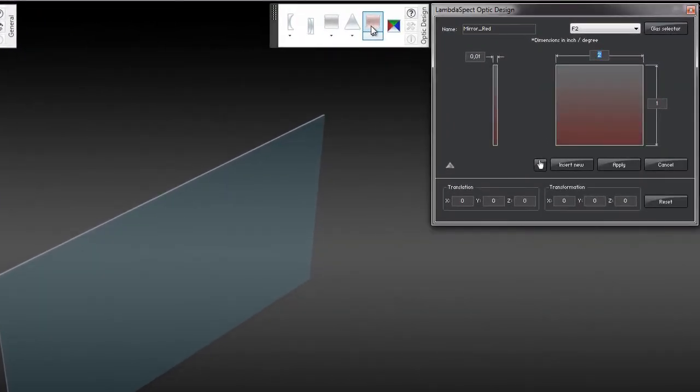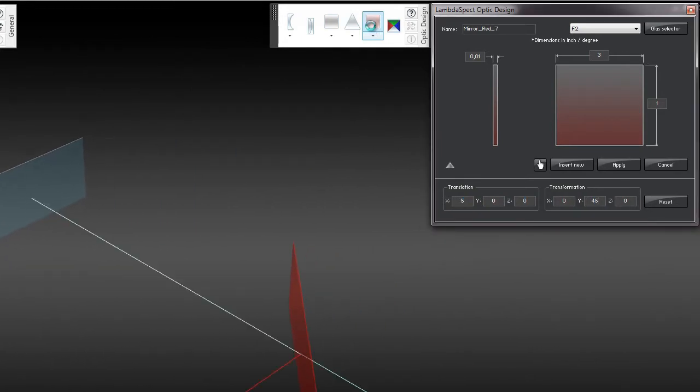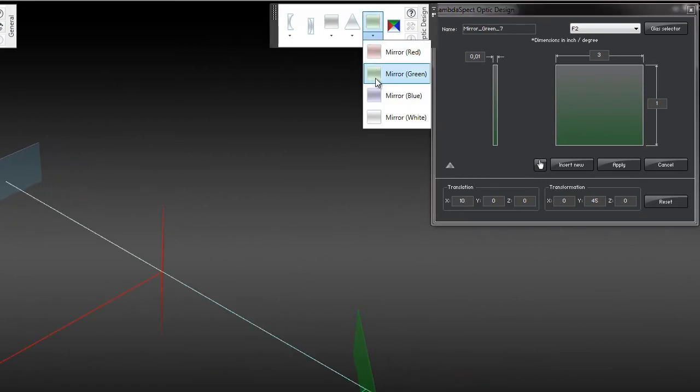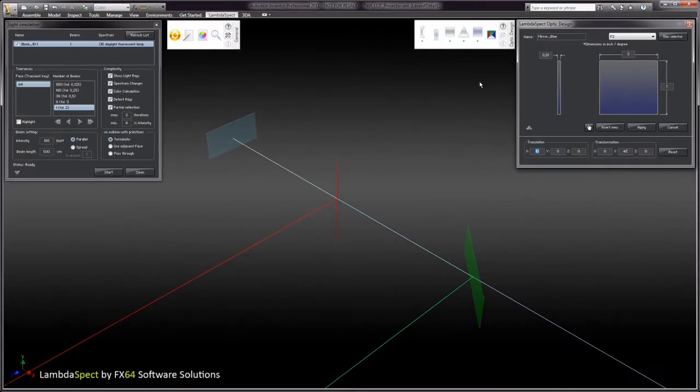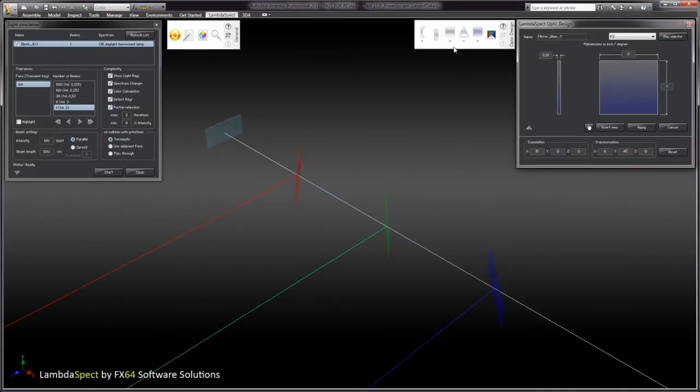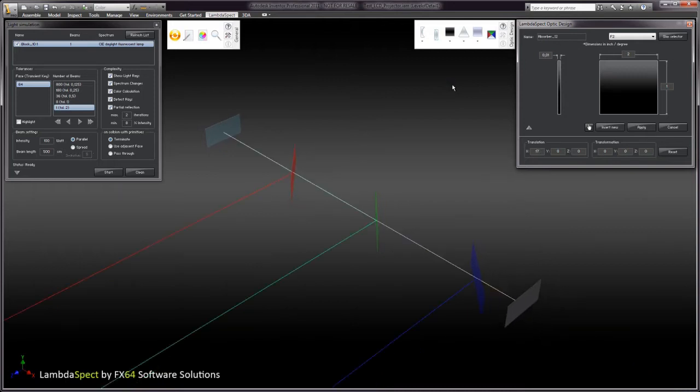When designing optical equipment, one of the often requirements is to filter specific wavelength ranges, typically red, green and blue, from common white light. To this end, we use the Optical Design Assistant functionality to quickly place some predefined coated mirrors to split the light. The direct access to the translation and transformation data allows you to design your digital prototype very fast. Finally, we'll need an absorber for the rest of the source light.